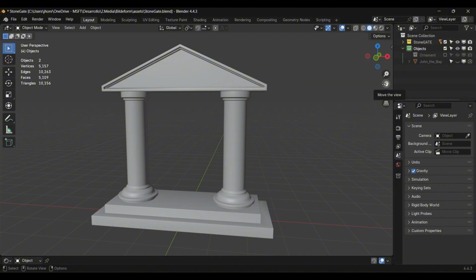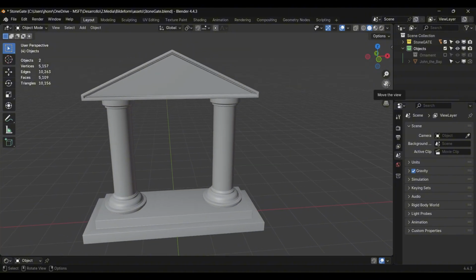assets that we can then leverage as alpha brushes in Blender Sculpt mode. Using a height map from a real 3D model as an alpha brush can dramatically streamline sculpting workflows. Imagine deriving surface details directly from existing geometry, then stamping or blending them into other meshes during sculpt. The benefits are truly impressive. You can quickly transfer architectural details, ornaments, patterns, or organic forms into your sculpt session without manual painting. So let's dive in and see how to do this.